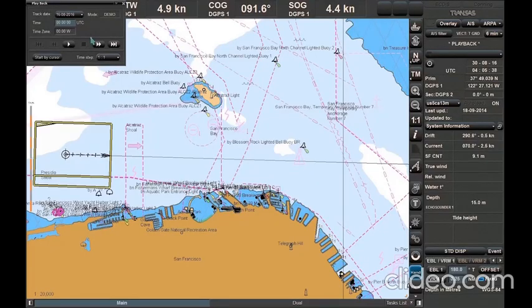Playback window. Click Time Step and select the Situation Playback Scale relative to real time. Click the Playback Start button and the Replay message will appear in the Mode line in the top right corner of the panel. On the chart panel, the ship's motion will be played back at the set time scale.